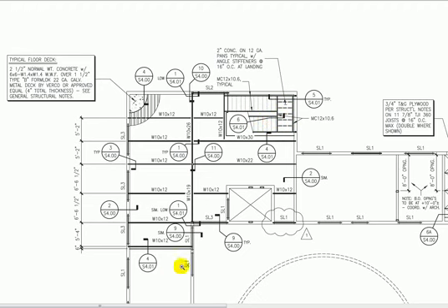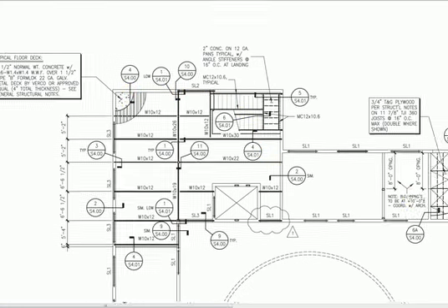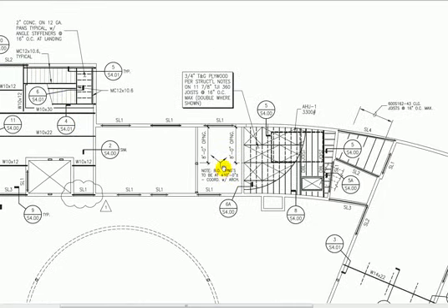So this is a little area. It's a concrete and steel framed little mezzanine. Let's pan around a little bit. Let's go over here. Now what I'm seeing here, tongue and groove plywood per structural notes on 11 7/8 TJIs. So TJIs, we'd have to go back to the notes, but a TJI is a plywood I-beam. So now we have wood construction over here.